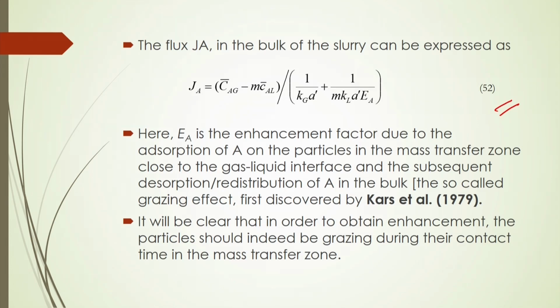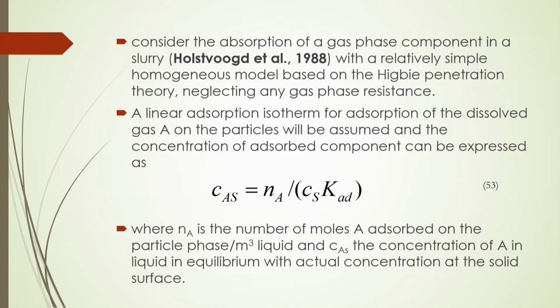And it will be obvious that in order to obtain the enhancement, the particles should indeed be saturated during their contact time in the mass transfer zone. And if you consider the adsorption of a gas phase component in a slurry with a relatively simple homogeneous model based on Higbie's penetration theory, and if you neglect any gas phase resistance there,